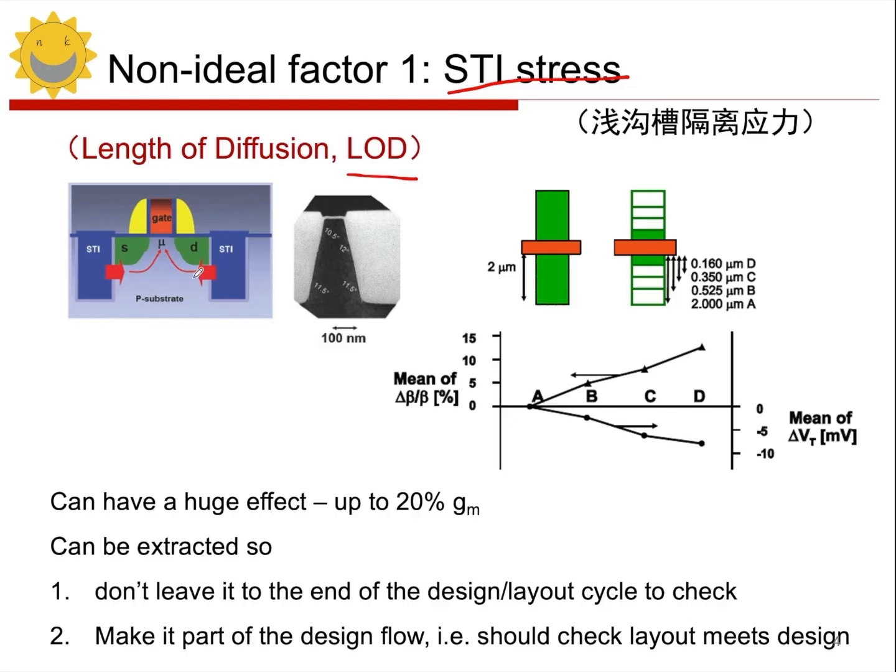Let's look at this picture. The area in the center is a MOS transistor, right? It is a MOS transistor. When we talked about the process flow before, we also mentioned that the MOS transistor must be processed in an active area, right? So the active processing happens within the active region, and outside of that region, everything is isolation, right? It's all isolation. Now, in earlier processes, this isolation was done using oxidation, right?